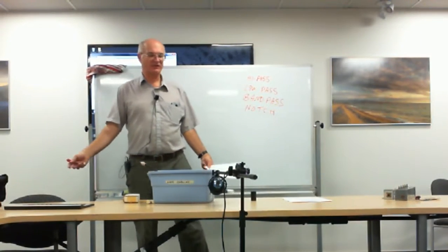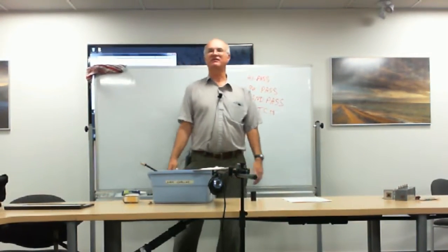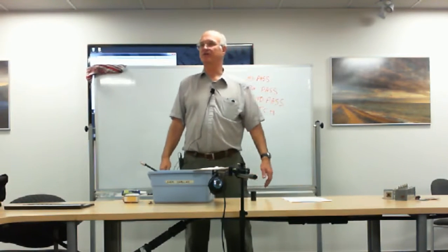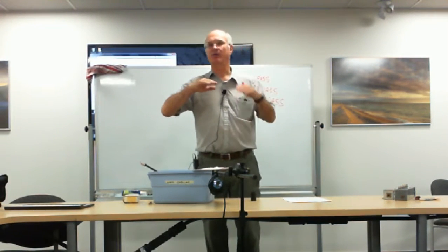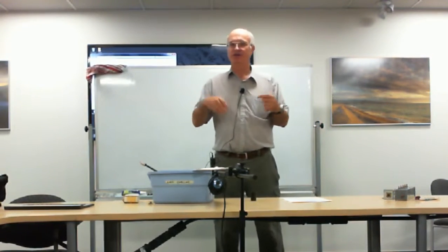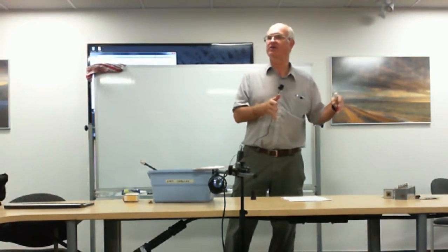A perfect example is that in our work, what we do is we evaluate FM radio stations. So sometimes we go to a site where there's 2 or 3 10,000 watt FM stations. What we want to do is get a measurement of the carrier level, and then compare that with a measurement of the harmonics or other spurious emissions in the aeronautical bands. The problem is that because we are so close, these other stations can overload the receiver when we tune up its sensitivity and we go just to 109 megahertz and above to look at the nav bands.